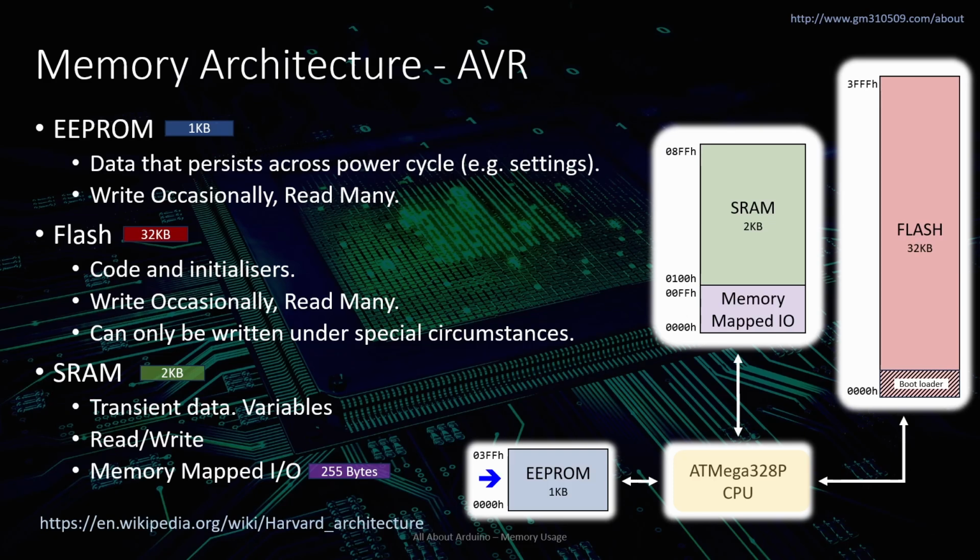Even though it's sort of considered to be on the same bus as this, I've sort of recreated it like this as more of a logical I/O, but technically this purple bit is over here on this bus. The other thing that I've drawn in here is the bootloader, and that's sort of configurable, but basically it sits at the bottom of memory here.